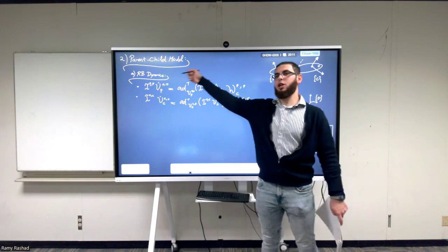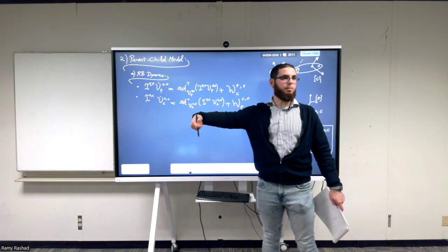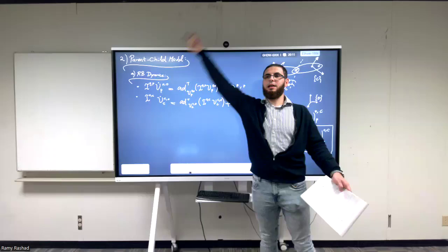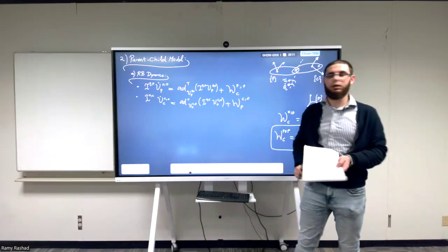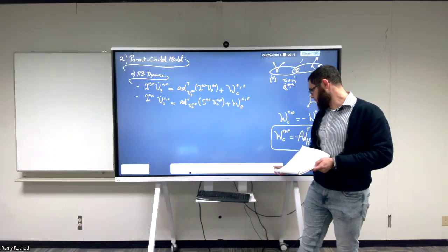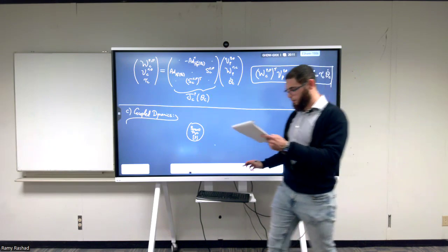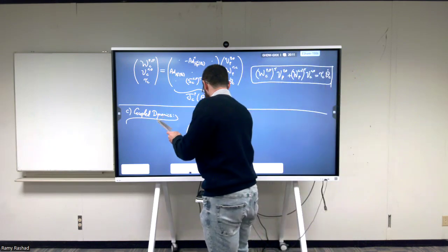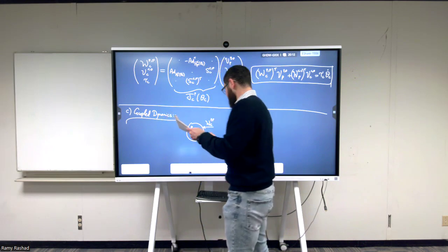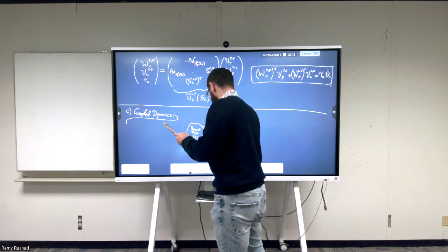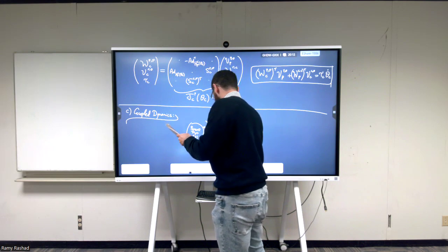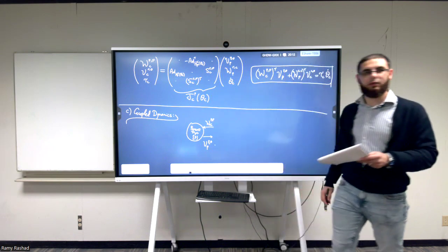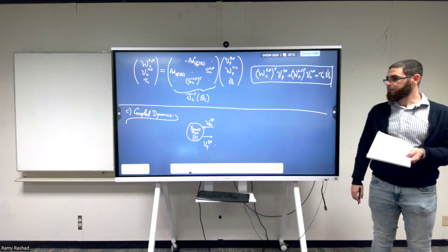Of course, it's a differential equation because it's a function of VP, so it integrates the V dot and then takes it back. You remember how we drew it before? So this is an equation that takes the wrench applied by the child to the parent in the P frame, and it outputs VP with respect to 0 expressed in the P frame.